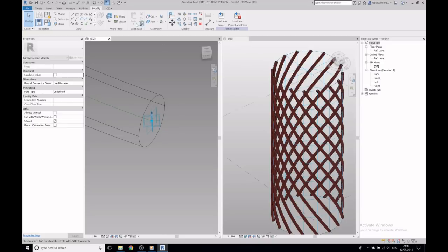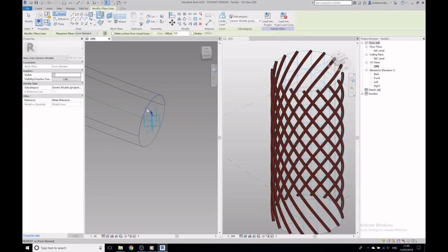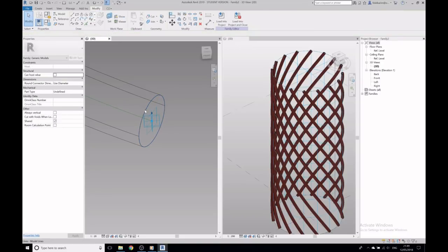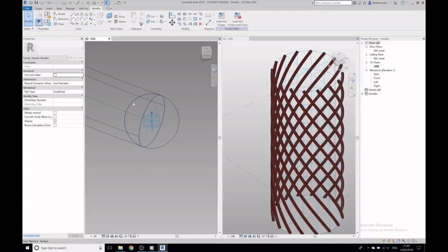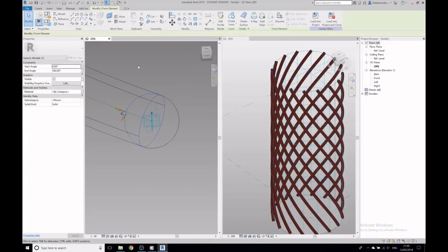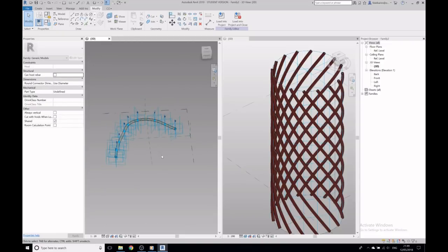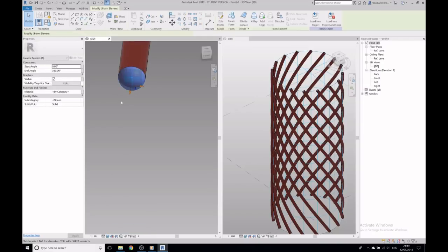And I'm going to do the same here. Set, face, that one. Draw a circle. Select the circle. Say create form, spherical. Yeah, it won't let me do that there either. Now, if I come to realistic mode, obviously those don't have materials on yet.